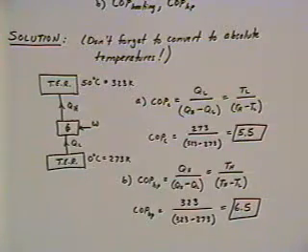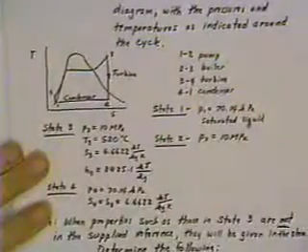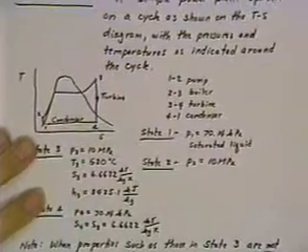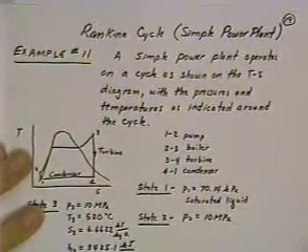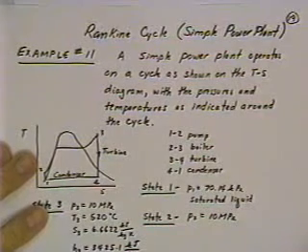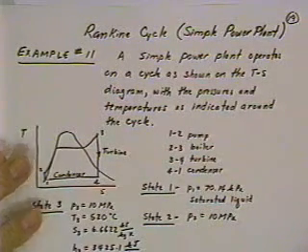And so what you'd like to have would be coefficient of performances that are in the neighborhood of 3 or 4 or 5 or something like this to ensure that you're delivering the heating or cooling as efficiently as possible. The COP is also related to things like the SEER that you see for air conditioners, but those don't have anything to do with the fundamentals of engineering exam, so we won't go over those.